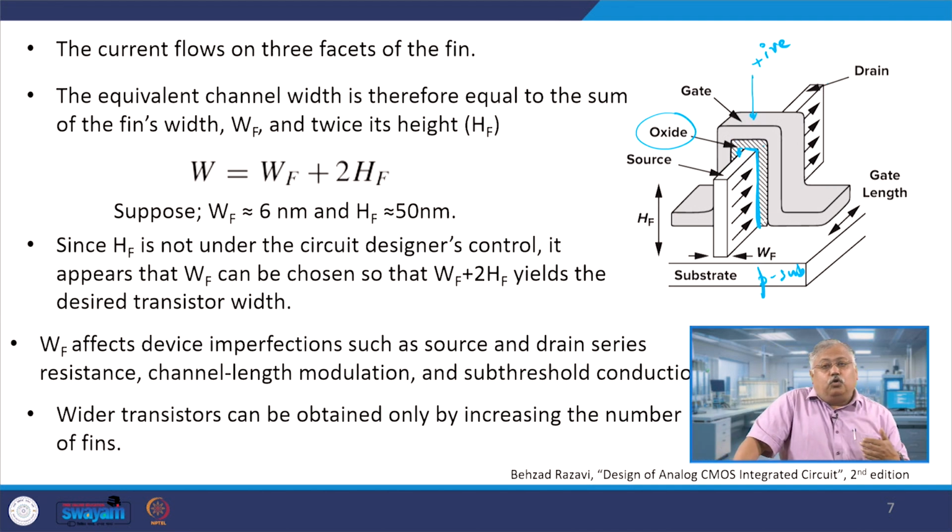So, though your channel length is said to be between source and drain, the effective distance which you see is between the gate. So, this is the gate length which you effectively see here.